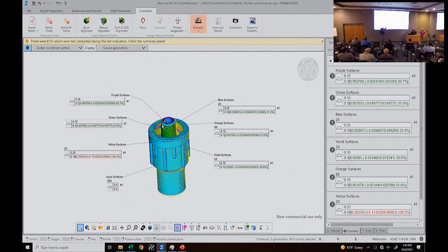It's luer fittings. Luer fittings, as you'll have run across them, are an ISO standard. From a syringe to a needle, it's a luer fitting. From your IV bag to the tube, it's a luer fitting. They all have a common ISO feature on the inside and then the customer design on the outside. That is an interchangeability thing: if one guy makes the bag and another guy makes the tube, are they going to fit together? The luer ISO standard guides you to that.